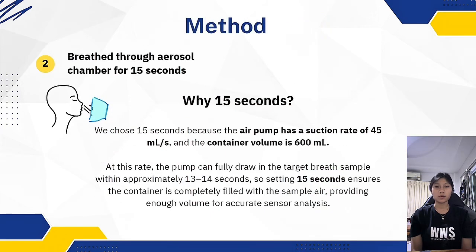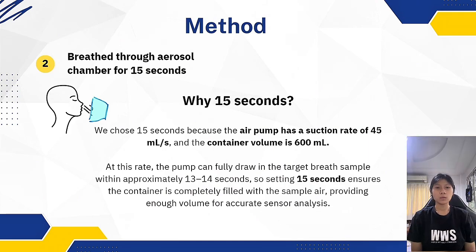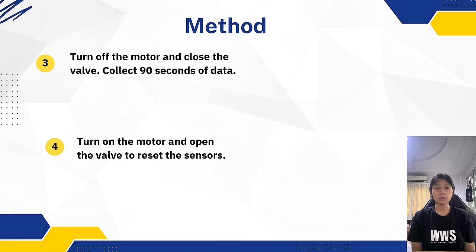You might be wondering why we breathe in for 15 seconds. That is to make sure that all the air in the container is sample air. For the third step, we turn off the monitor and close the valve. Then we wait for about 90 seconds to collect the data. And lastly, we turn on the monitor and open the valve to reset the sensors.